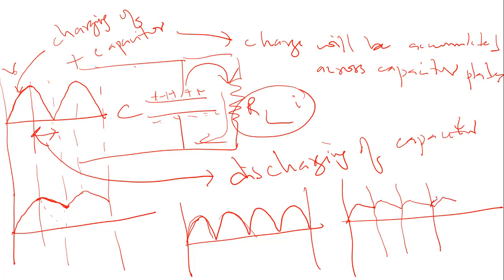Okay, so the charging process will occur, and then the discharging of the capacitor will prevent the voltage across the load resistance, or the current across the load resistance, from dropping down to zero. So it will sort of flatten the signal like this. That means the changing component, the ripple component, which is the alternating component that rises and decreases, is now filtered out.